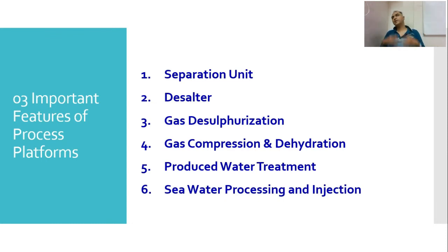Separation unit. From the name itself you can make out that it is the separator. The separator is a part of this separation. So what is this separation? When we get the well fluid, it is a mixture of hydrocarbon liquid as well as gas, because when the hydrocarbon comes out, it has dissolved gas in it, similar to drinking soda.